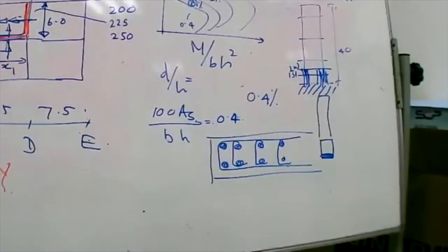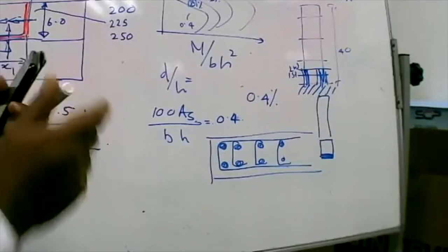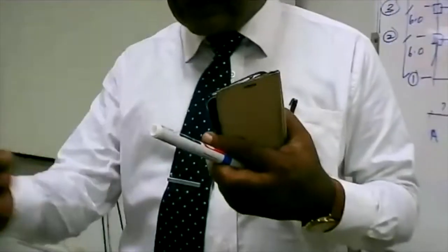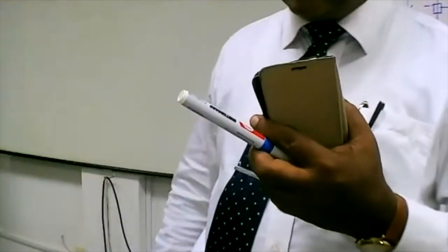Otherwise, theoretically, what you need is only the spacer bars, which means for every 0.4 meters or so, you'll have a bar connecting the 2 mats of reinforcement.